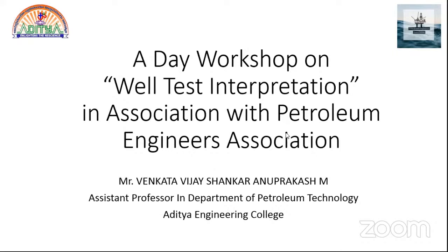Okay, sir. Next question. How accurate is pressure transient analysis using surface-based acoustic fluid level, surface and casing pressure measurement? See, accuracy all depends upon the flow rate record. If the flow rate record is accurate, obviously our results are accurate. If the flow rate you are recording is not accurate, obviously it will affect the accuracy.